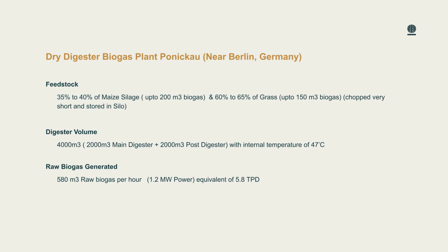I'm doing biogas more than 30 years now, and there's a misunderstanding about the digester. The digester is completely filled. It's a static process. You feed it every hour, you take out substrate every hour, you keep the temperature very close to 45, 47.